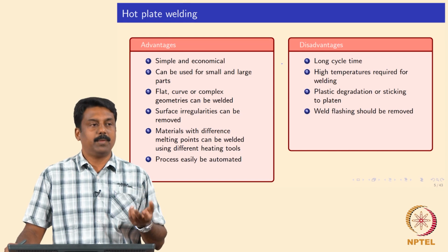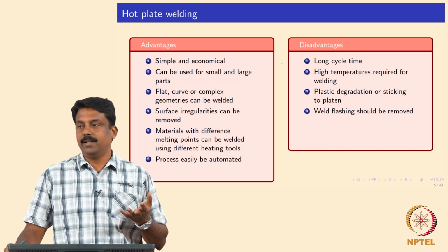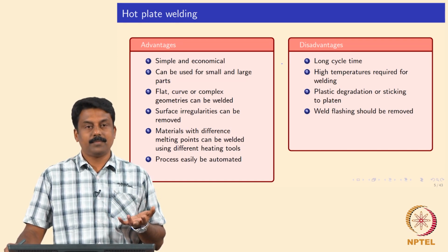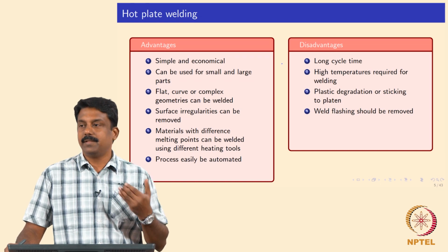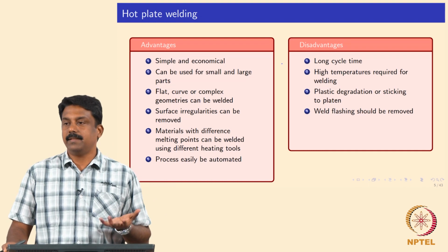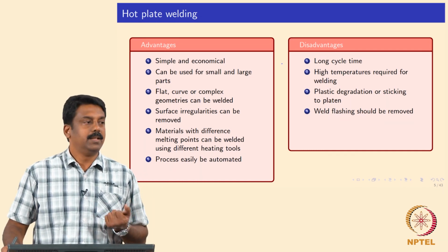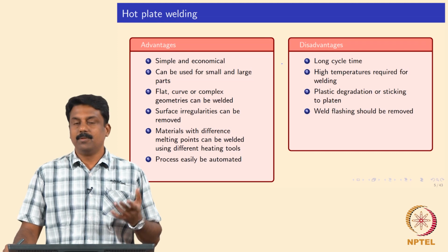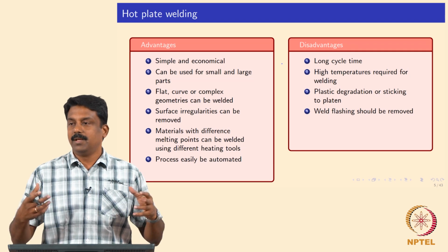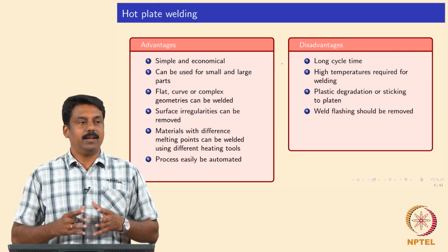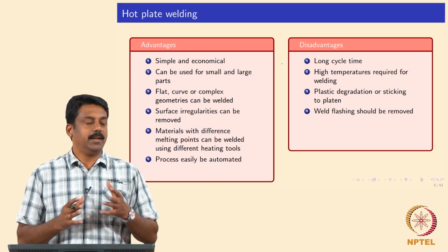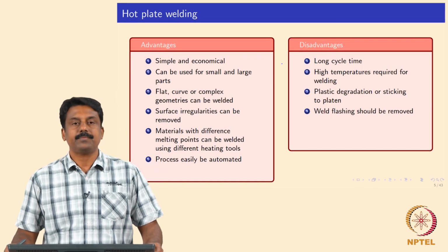In adhesive bonding, preparing the surface is extremely important, and we sometimes have to do cryogenic treatment. The surface has to be polished very well, and then also treated in dry ice at -10 degrees. We generally do it in our lab when doing adhesive bonding. Those kinds of complex preparations you do not need here, because you take a hot tool, press it against the interface, the interface is molten, then you remove the hot tool, press again, and you have a solid joint.